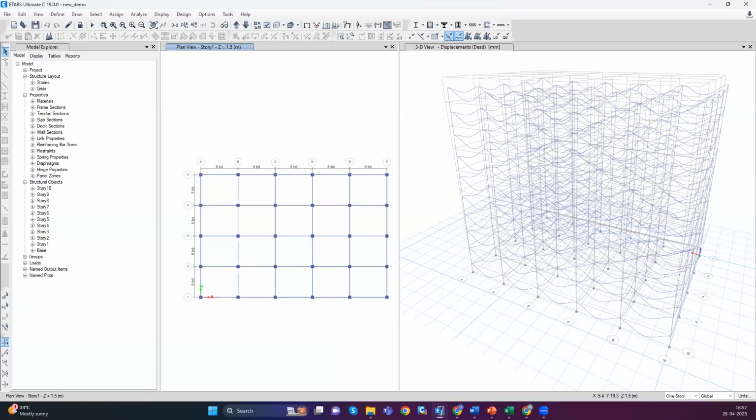Okay. And this is not a question, just one comment. Mr. Millen is asking how to determine the plastic hinge length. My answer to that is, there is one research article by Mattock in the year 1967, and it is most commonly used in the research fraternity to calculate the length of a plastic hinge. And the equation is very simple.